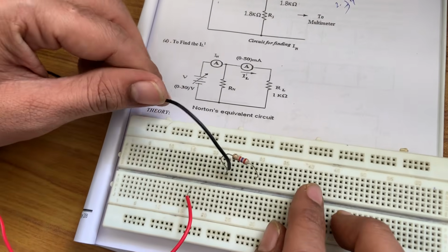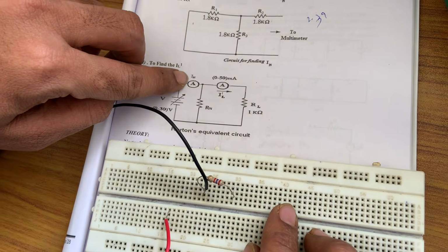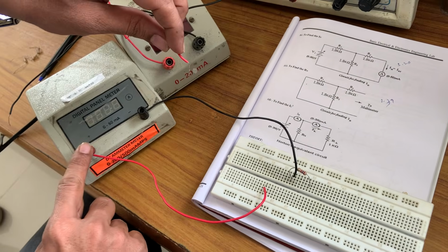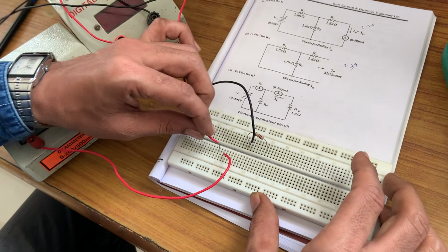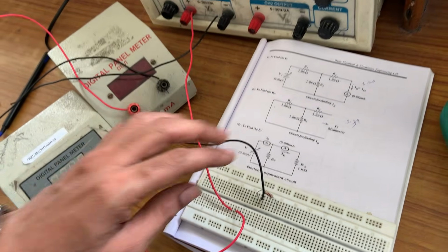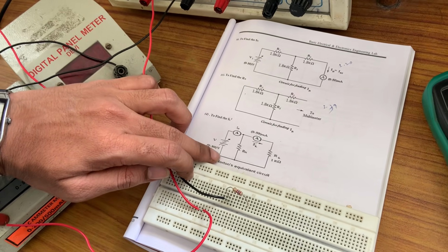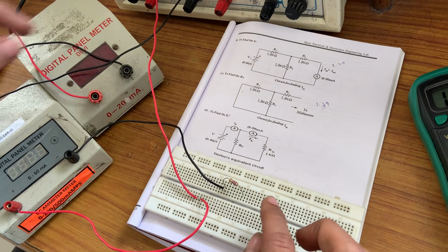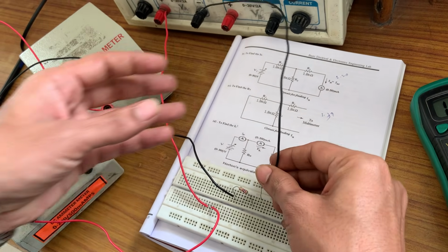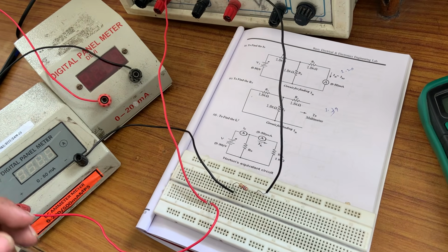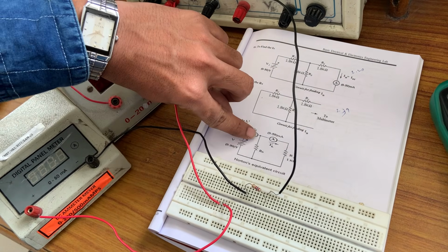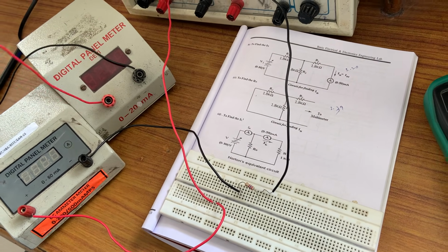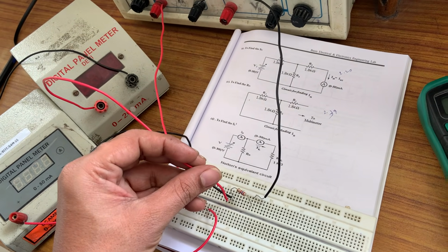Now if you observe here, RPS positive is connected to the ammeter positive. Here this is my RPS positive. Next see here, RPS negative is connected to the Rn second end. Now this is my Rn second end. Thereafter Rn first end we need to connect another ammeter positive. Now say this is my second ammeter positive, connected to this place.